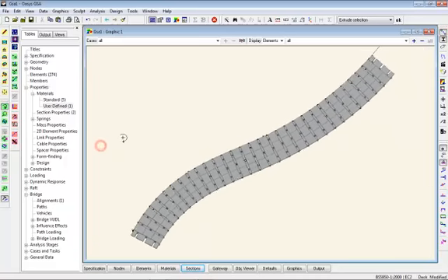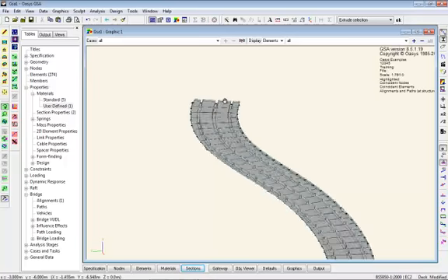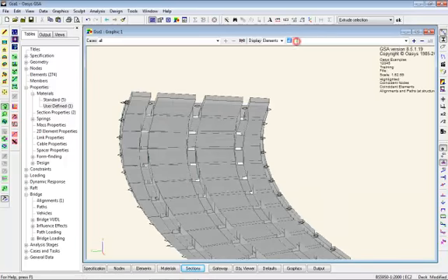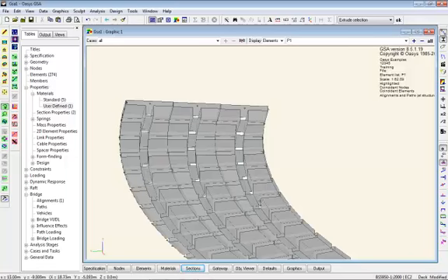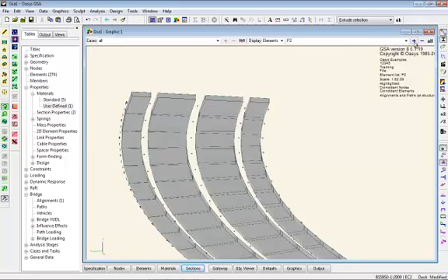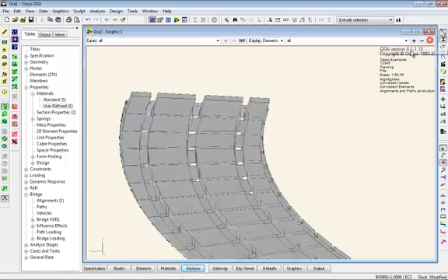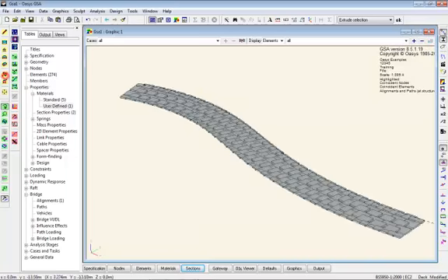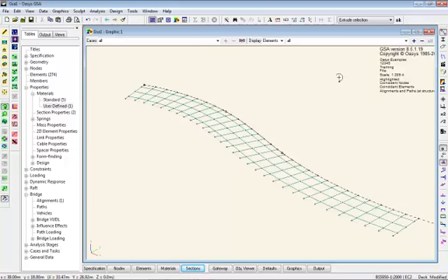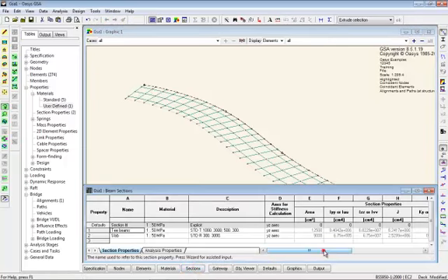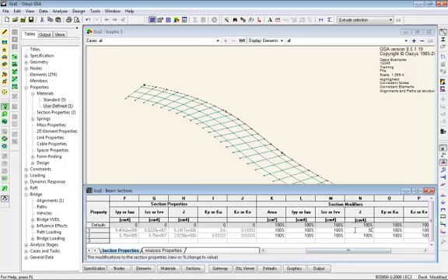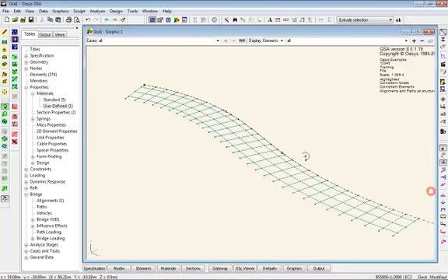So we should now have a nice grillage of the elements, and we can see we have the T-beams running along the bridge and the slabs running across. Wonderful. Okay. Now, to minimise torsion in these sections, I'm just going to reduce the torsional stiffness. Not eliminate it altogether, obviously, because we will get a certain amount of torsion, but reducing the torsional stiffness puts more moment into the major axis, which is where I want it.